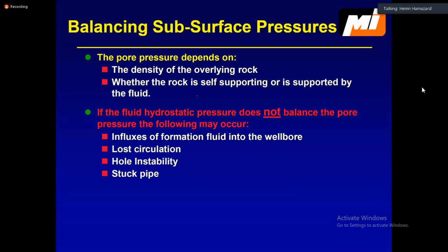The calculation for that is pretty simple, and it's been simplified in the oil industry. It's just a conversion factor, which is 0.052, times mud weight in ppg, times your vertical depth, not deviated but vertical depth, in feet. Then you can know your hydrostatic pressure. If you are at a certain depth, the depth cannot be changed, obviously, and the conversion factor is a fixed number. The only thing we can change is the mud weight. So that's why it's very important to have a proper mud weight.